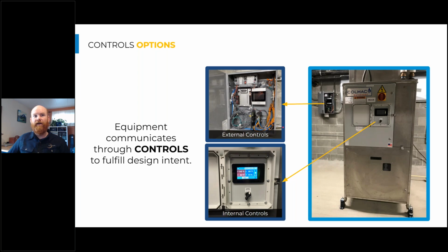But there are also external control systems that can integrate with the heat pump water heaters, as well as other components in our commercial heat pump water heating system. So if we have multiple backup devices that are going to help our heat pump water heaters on certain days of the year or in unfriendly climate conditions, the external control system is typically working very similarly to the internal controls of the heat pumps, but we need to ensure it's set up correctly for that heat pump water heater.